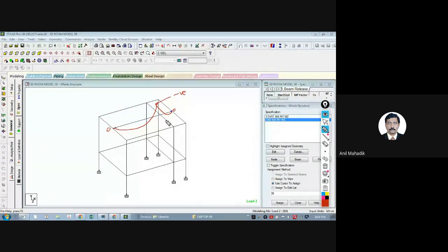Generally, we expect continuity in the beams if there is availability. So tell me why we are not doing it simply supported. Why do we want continuous? Economical design, sir. Economical, because if you take simply supported, then this will be WL square by 8, and this will also be WL square by 8.